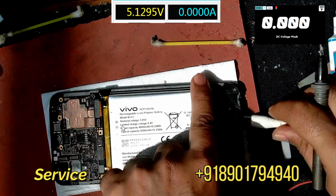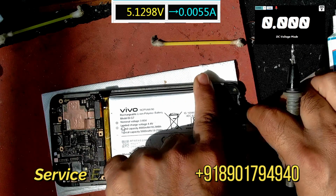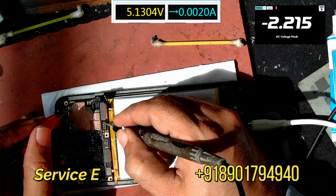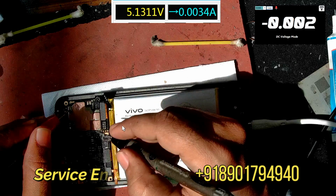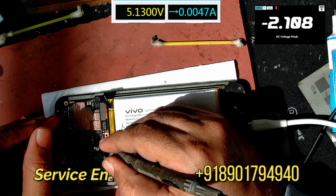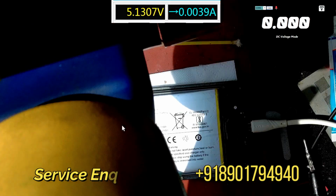Now I'm connecting a charger. Look at the charging ampere meter. Now charging starts and the battery is disconnected. Now we check on VBAT. It's 2.1, 2.2, right? Now on VPH, let's see whether VPH is generated or not. VPH also 2.2 volts, right? 2.1. In normal cases we get a minimum of 3 volts.